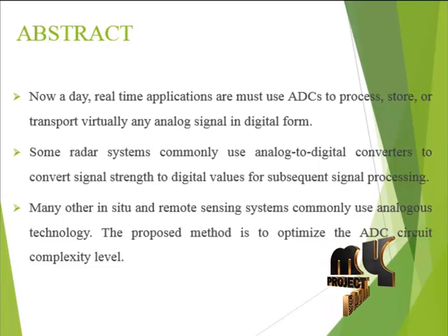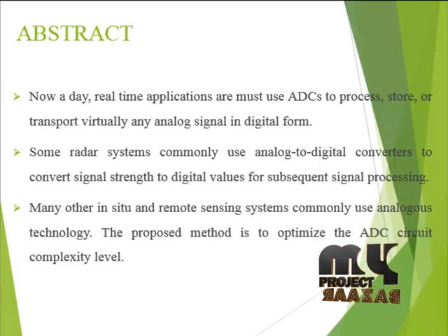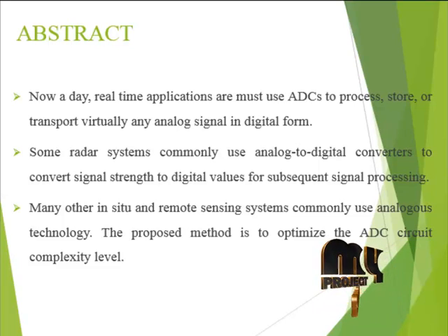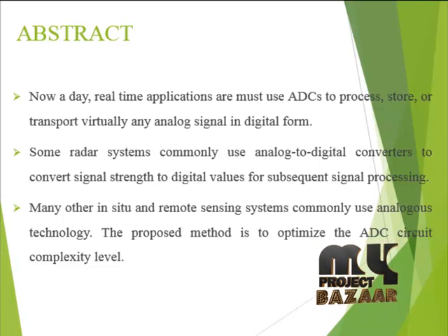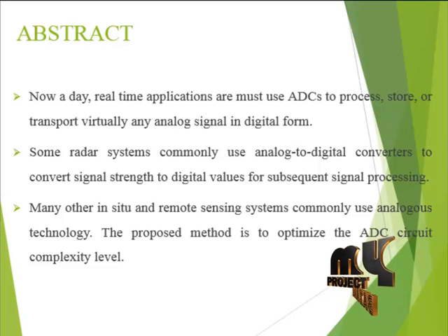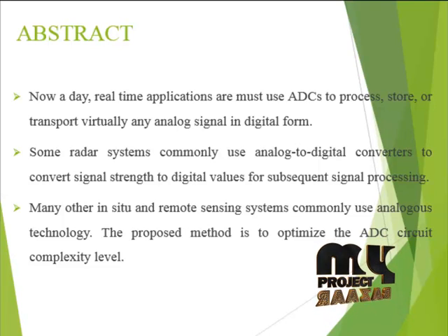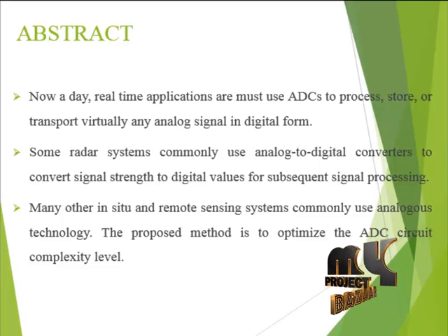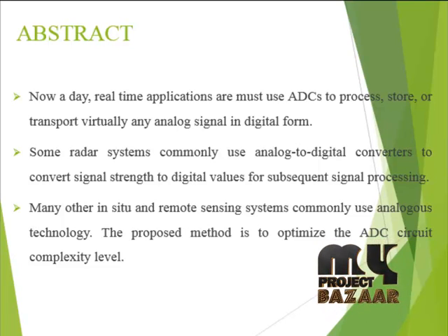The maximum sampling rate required for sensor applications is usually only a few megasamples per second, which is smaller than the typical sampling rate at which a pipeline ADC shows its best conversion efficiency. For any type of sensor, we are going to convert the signal from analog to digital in real time. We propose the pipeline ADC as a potential candidate for ultra low power applications.